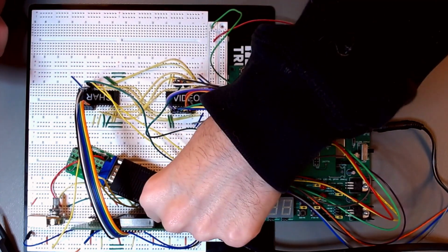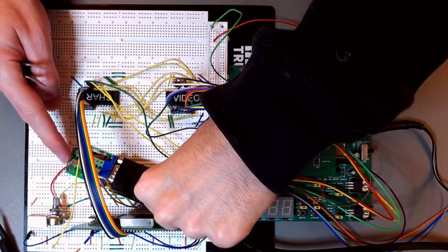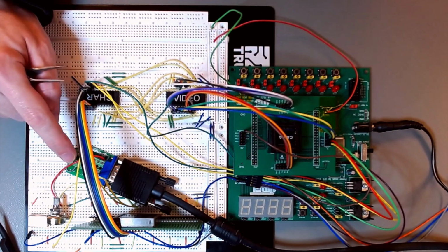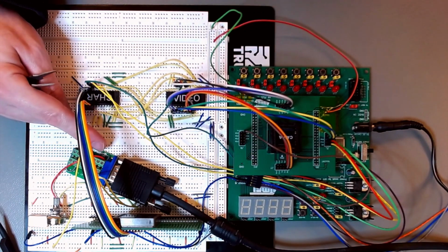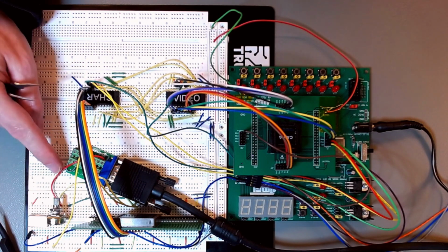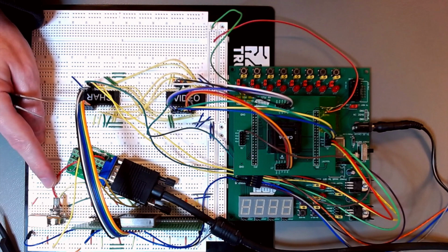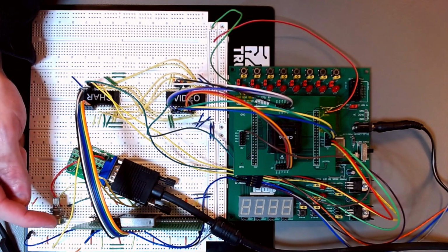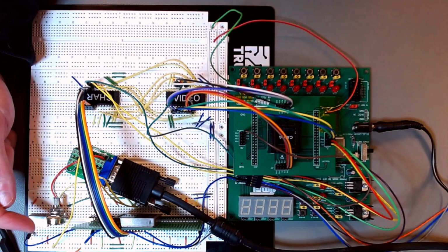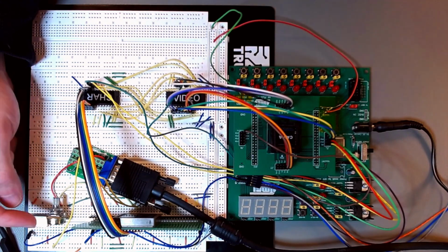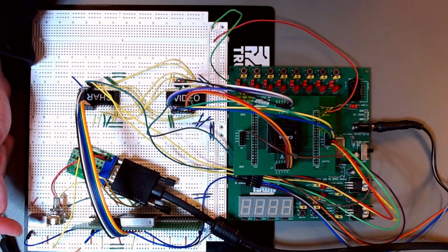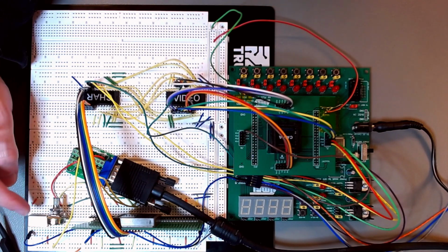I connected the VGA cable here on this connector. I have the red input of the RGB signal wired together with the green and the blue, so this is the sole color signal. It comes from the mid terminal of this potentiometer here, which is playing for now the role of analog video circuitry. It will not work well, but it will work enough, I hope, for us to see whether the right things are on the screen.